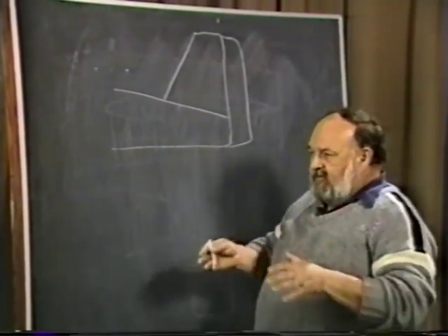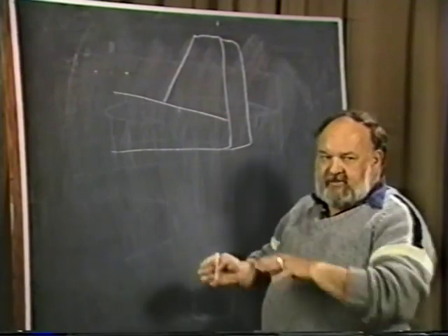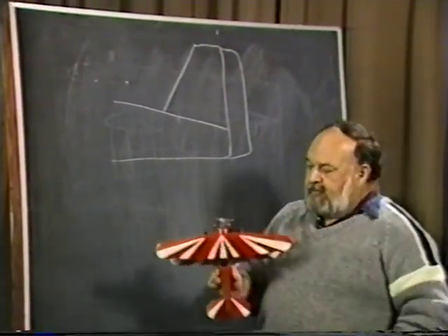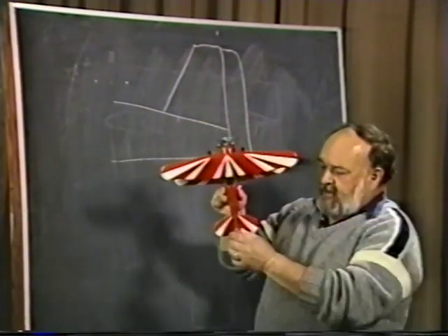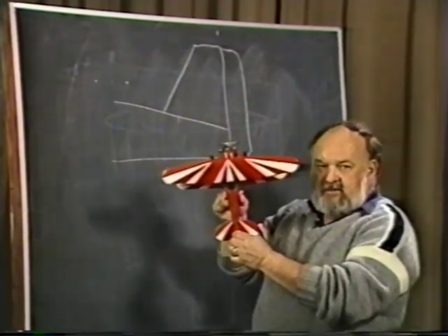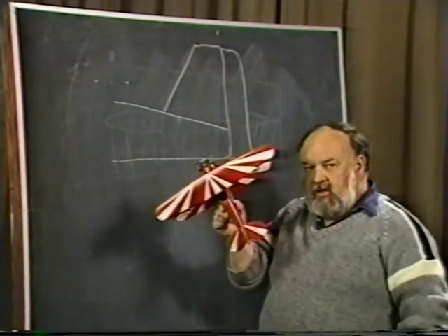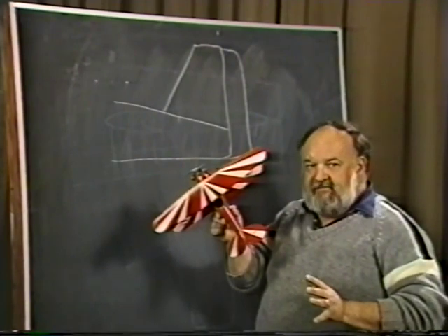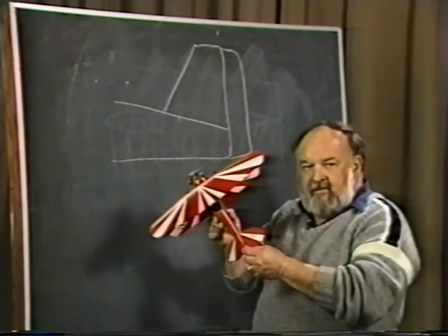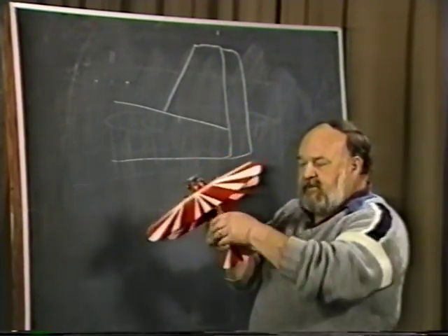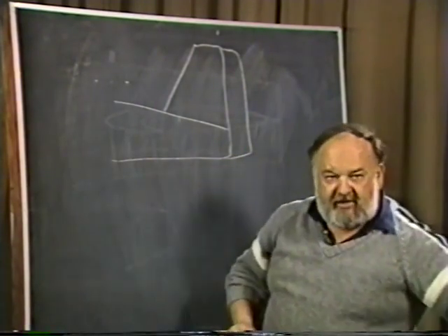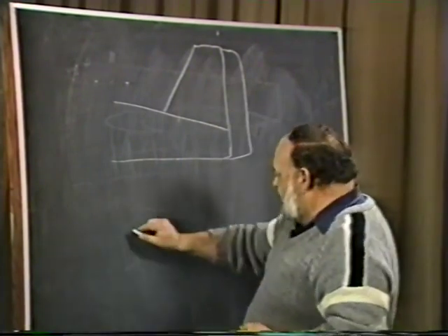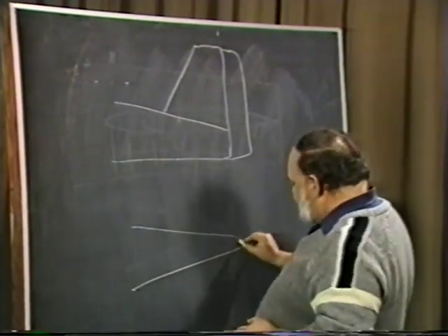When you're dealing with ailerons, when you're dealing with elevators, you're maneuvering, you're doing a series of things. In regards to the fin and rudder, primarily you want this airplane to fly straight through the air. You want this thing to give you directional stability. And when you do yaw, you're yawing under a controlled condition, a side slip kind of a condition, and you're being forced to fight this thing with the rudder by twisting the rudder in the direction to cause that surface to go over. So what can happen is, and let's take a look at it from a top view here.